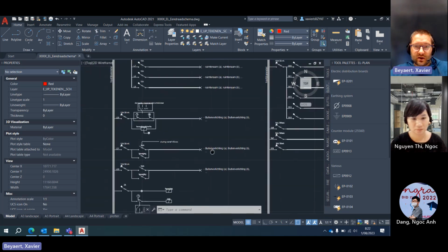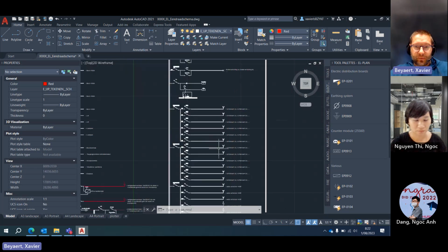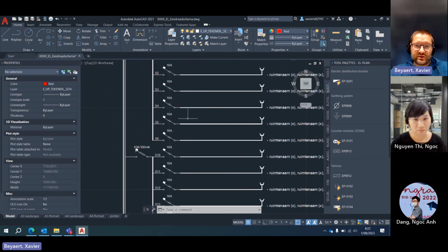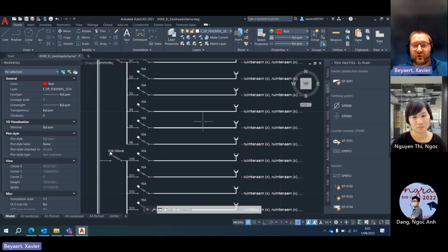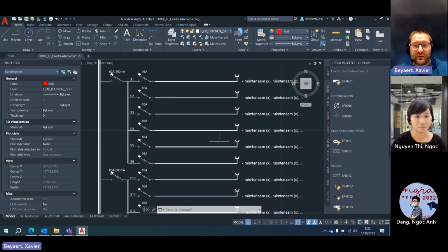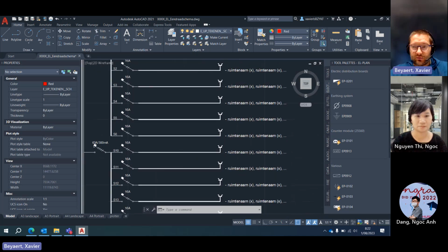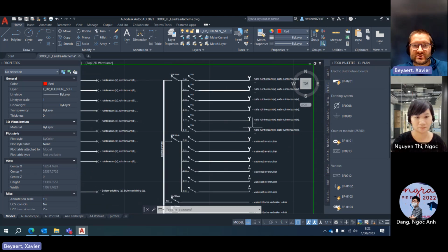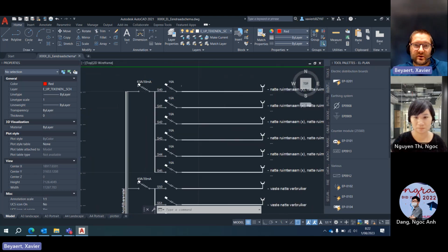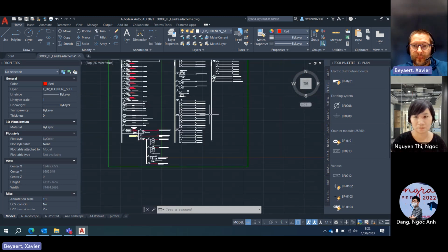Here's some explanation about outside lighting and so on, and then you have again the sockets, where for sockets we say okay, 6 departures after one differential. That's the main thought. So again, if you have a fault, you don't lose the whole installation, but you only lose 6 circuits and not all. Then each time it's the same. For wet areas, we use 30 milliamps. For dry areas, it's 300 milliamps.